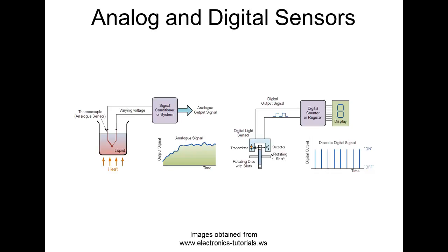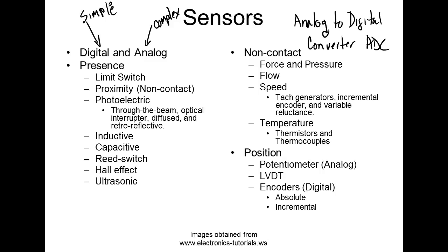All these proximity sensors over here on the left, except for limit switches. Limit switches are truly digital. Through-beam is truly digital, but diffused and retroreflective sensors are usually analog sensors that we have the ability to set a threshold on. And I'll show y'all that when we go look at some of our manufacturing lines.